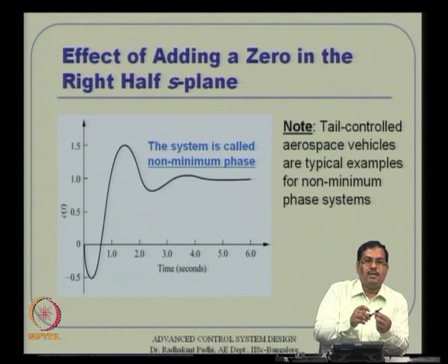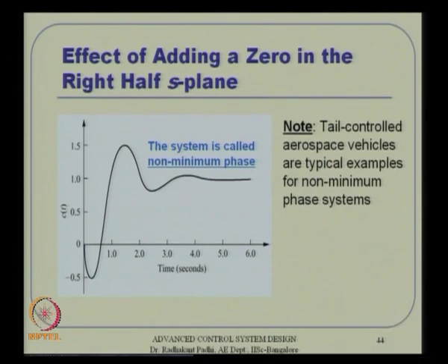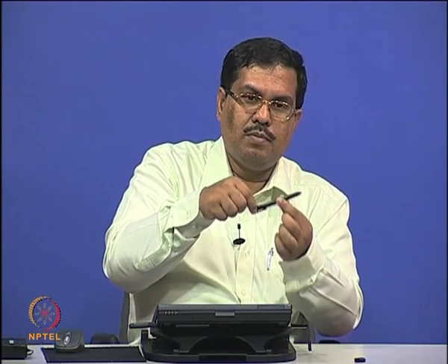That means initially you are applying a force downwards, which is acting on a rigid body, so the entire body will drop down and then move up. It goes a little down, but simultaneously it is also rotating, and then it shows a large angle of attack. It will have more lift and then it will start going up. That is what normally happens.